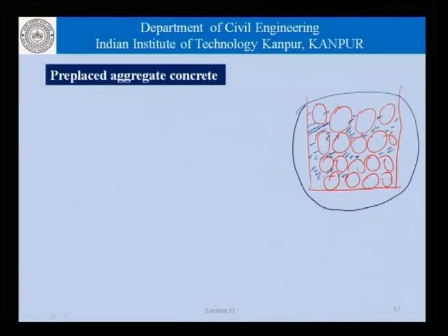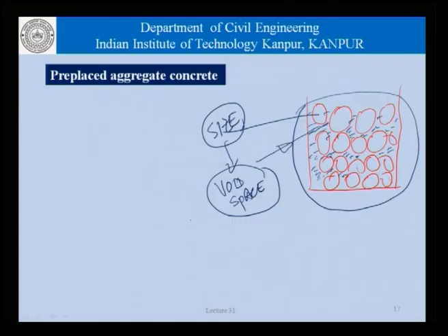Now, when we are considering the requirements of the grouting material, that is the mortar that we use to fill this system, the principles of grouting would apply. That is, we would be interested to know what is the size of the coarse aggregate and the particle size distribution, which will determine the characteristics of the void space. If we have very small particles, the amount of void space will be different compared to having larger particles.